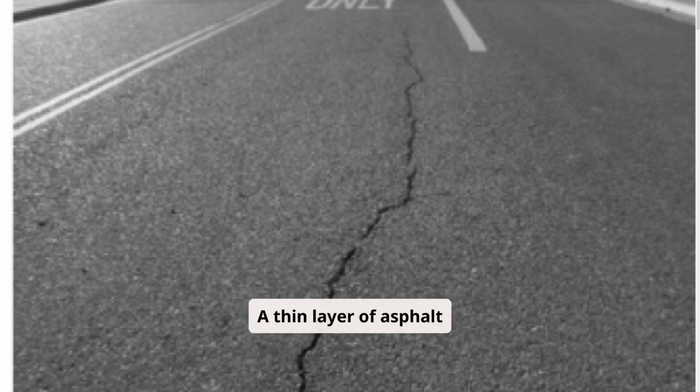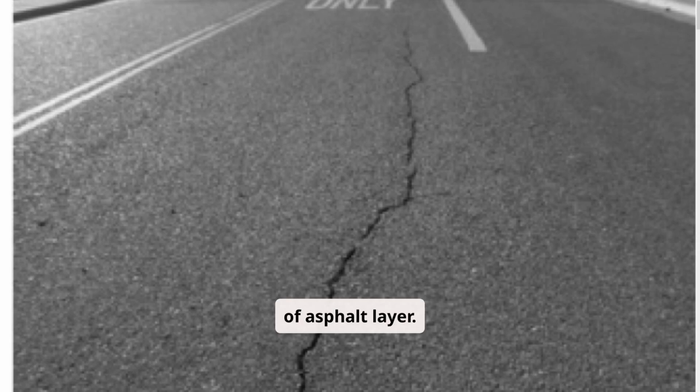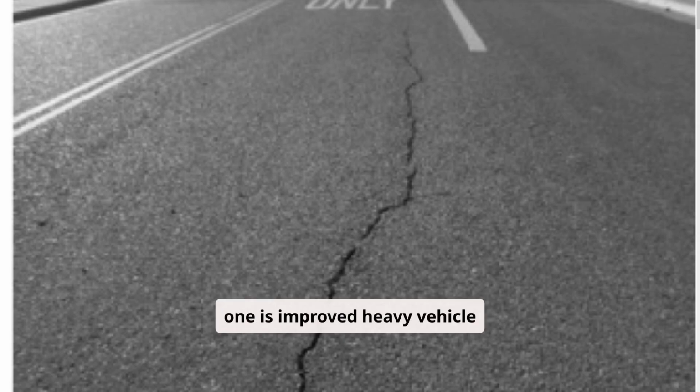A thin layer of asphalt may be replaced if the cracks do not penetrate to the full depth of the asphalt layer. Otherwise, full-depth rehabilitation may be required. 2 major options are available to mitigate or avoid top-down cracking. The first one is improved heavy vehicle loadings control, and the second is improved asphalt surface courses.